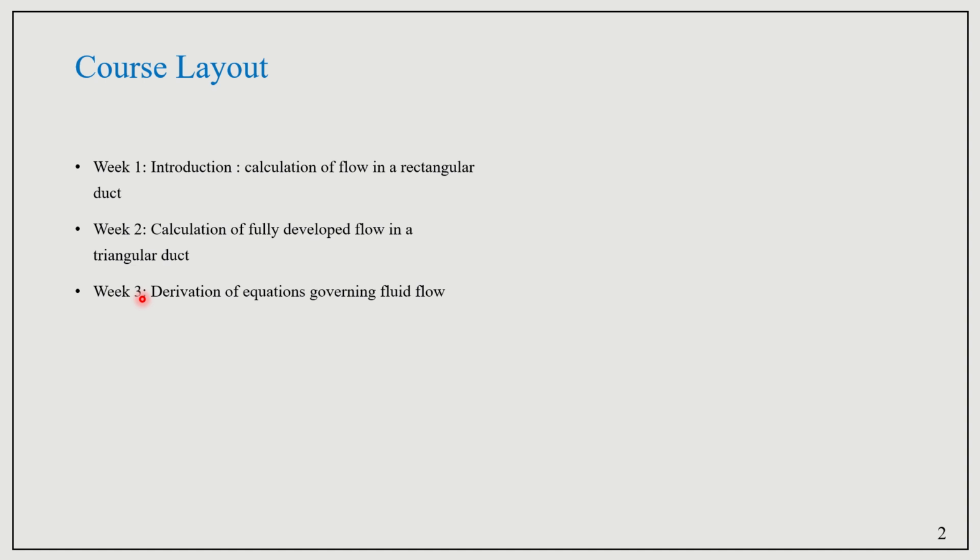First we define the system, that is, we define the geometry of the system, and later we divide the system into smaller grids, and in each of those grids we solve the equations and we get fields like velocity fields, and if temperature is involved, we get temperature values. The approach we use to get the grids and do further calculation will be the finite difference approach, finite volume approach, or finite element approach.